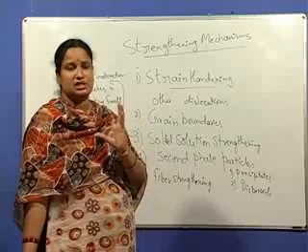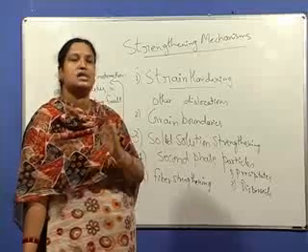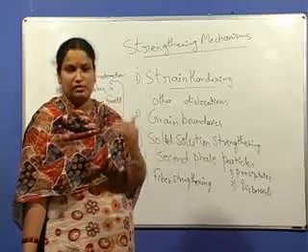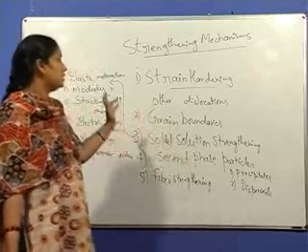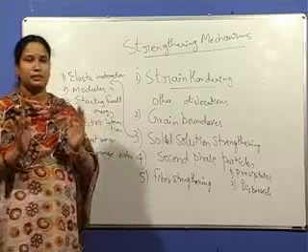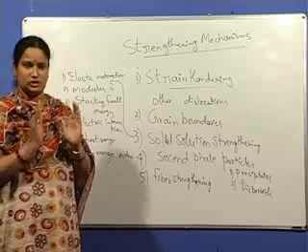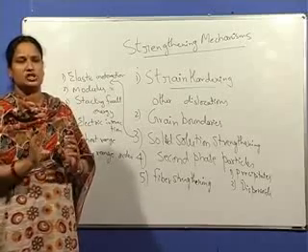This elastic stress field depends upon the misfit of the solute. The larger the misfit of the solute, the larger is the hindrance to the dislocation motion. That is elastic interaction, mainly because of the misfit of the solute. The stress fields which surround the dissolved elements cause hindrance to the dislocation motion.